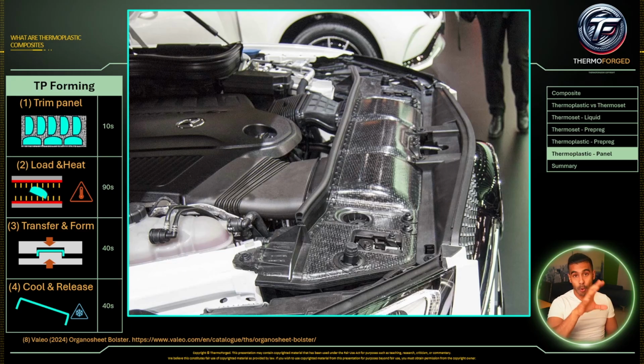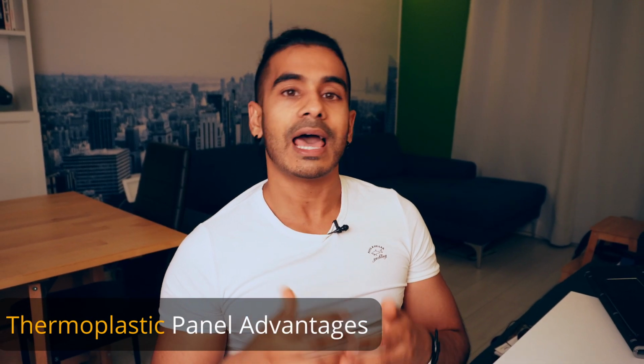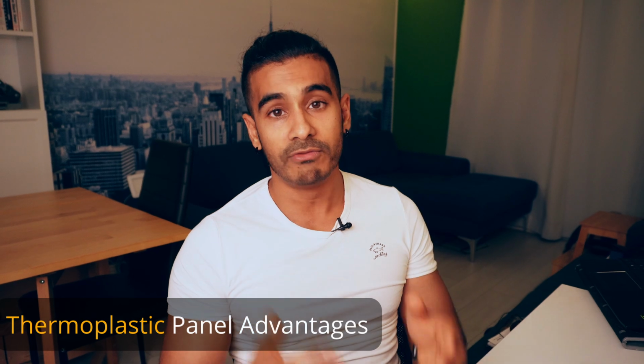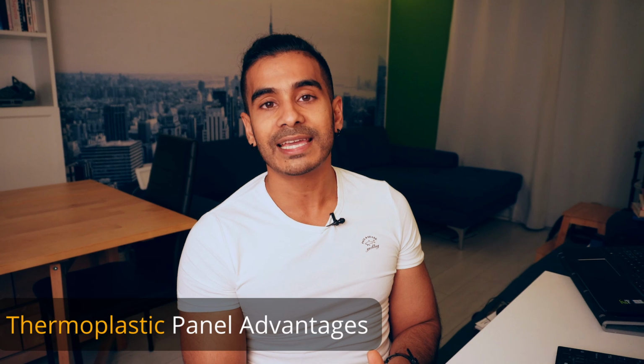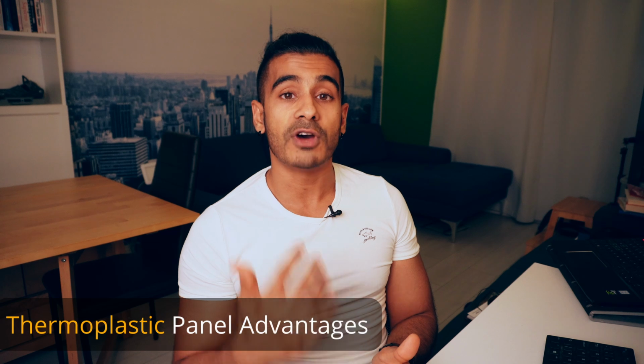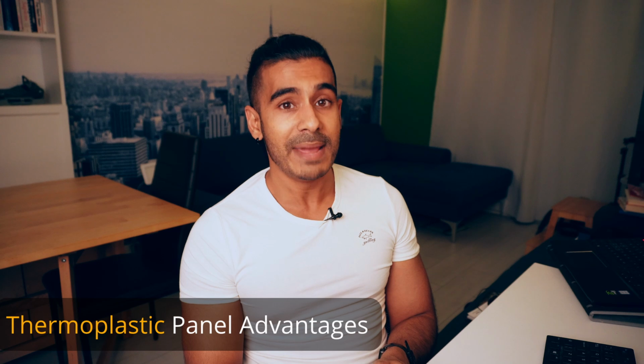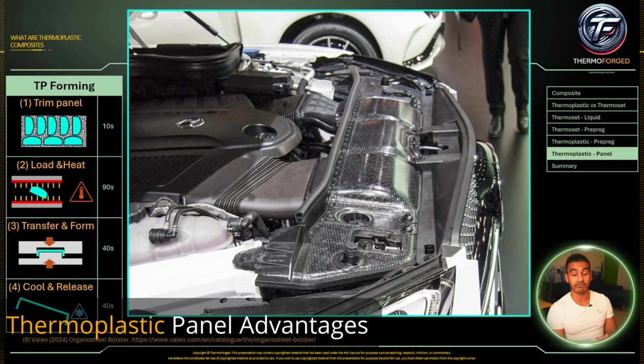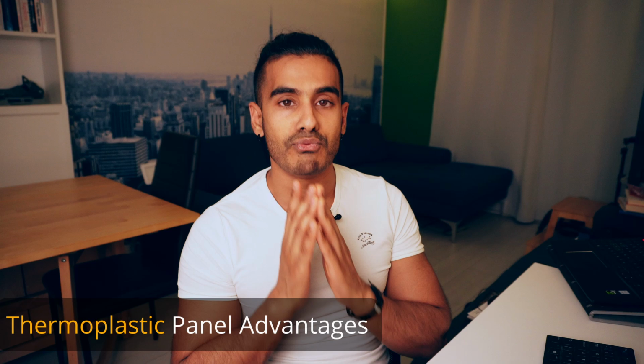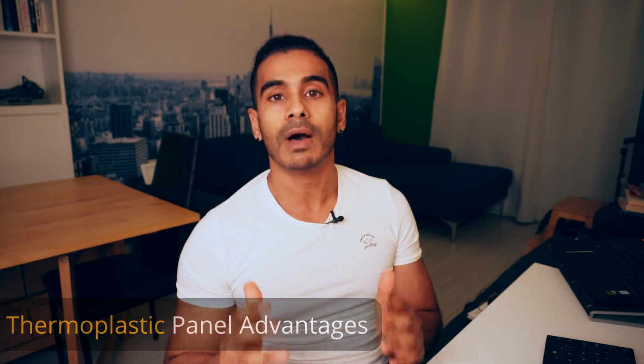And this whole manufacturing process, if you were to do it, for example, using a thermoset material, just the layup of the material and then the curing and then the overmolding, which is a bit more complex, all of that, you're thinking in terms of hours and hours, and I'm talking like tens of hours, which is very costly, whereas this manufacturing process is done literally in minutes. 3 to 5 minutes, you can actually make this part, which is incredible and makes it really suited for high volume manufacture.